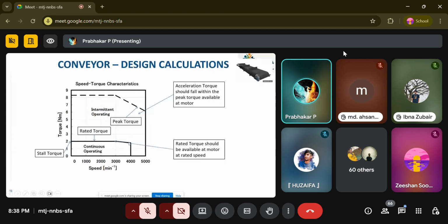After 3, it is getting reduced to 1.8 or 1.7 Newton meter. One more thing I would like to highlight here is stall torque. At 0 RPM, the motor has many magnets inside which resist the motion, and also many seals to avoid leakages, and many parts in contact like bearings, which have their own friction. So the torque required to rotate on its own is the stall torque.